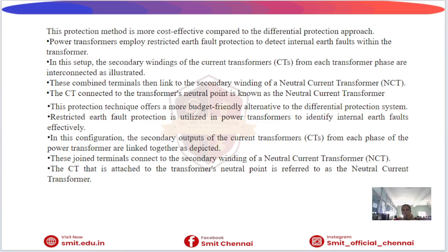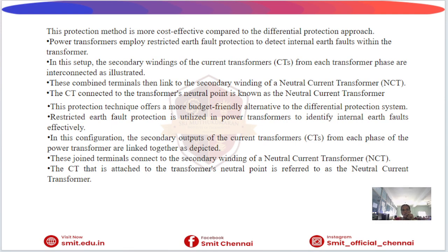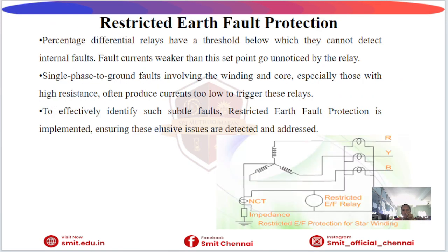Working of REF protection. CT outputs from all phases are connected together. They are linked with a neutral CT. Any imbalance indicates an earth fault, so the relay trips. The relay sends a signal to the circuit breaker, and the circuit breaker trips the circuit, so that we protect the transformer.